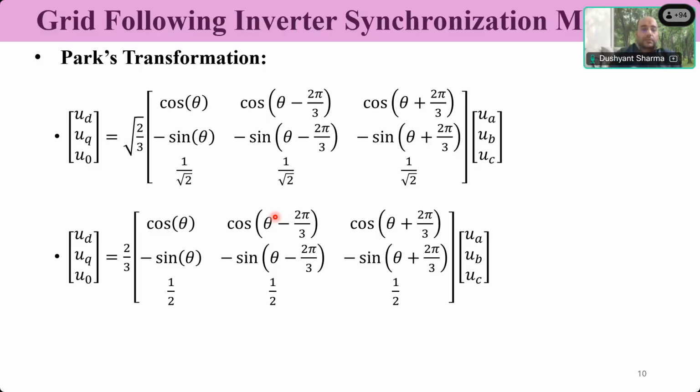They all are just mathematics. So what mathematics we choose is in our hand. We are controlling the peak or we are controlling the RMS, it is in our hand. So accordingly, the formula can get changed. The point is we have to convert to two DC quantities, of which one is in phase and the second is in quadrature.